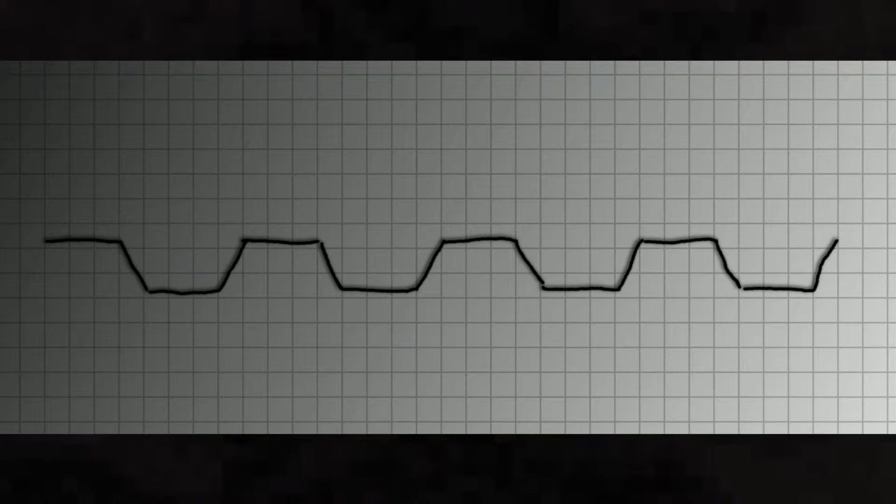The clock signal has two parts. The first half is low and not so important. The second half is high, and that is when the receiver evaluates the data line. Now here's the important part. There are 4 ways for data to go through the bus while the clock is high. Staying high all the way, staying low, falling while the clock is high, that is also called the start condition, or rising while the clock is high, also known as the stop condition. The first 2 conditions are used for data transmission, the second 2 for communication control.